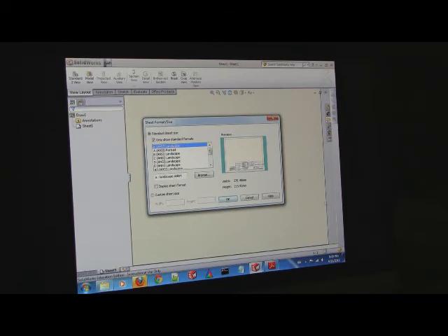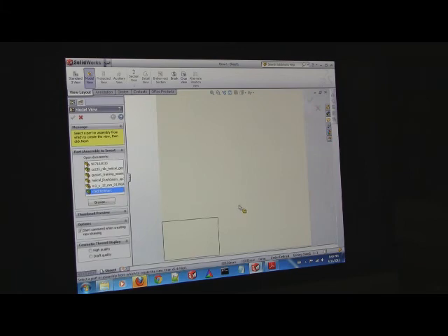Awesome. However, we're laser cutting stuff and we have a 4-foot laser cutter. So if you send me an 8.5 by 11, it's going to look very strange to me. I will not accept that because I won't be able to visually tell if you've put it in the right orientation. So I can just tell you, because I've done this a bunch, 48 inches safely is 1219 millimeters by 1219 millimeters. So custom, width and height are both 1219 millimeters, and hit OK.